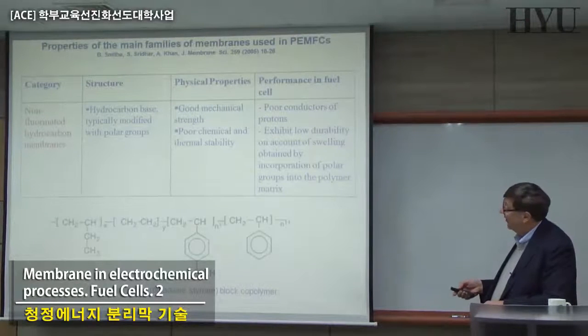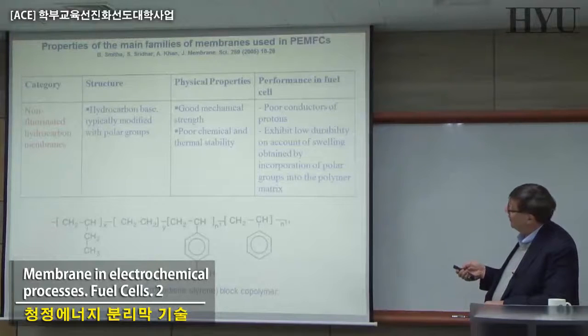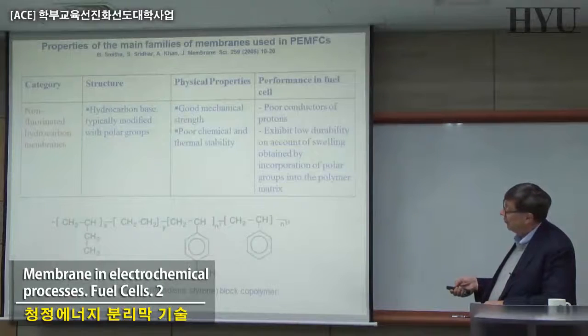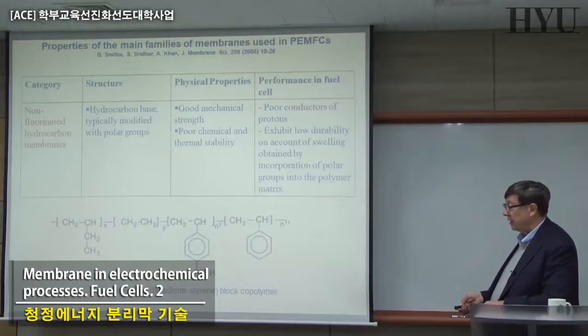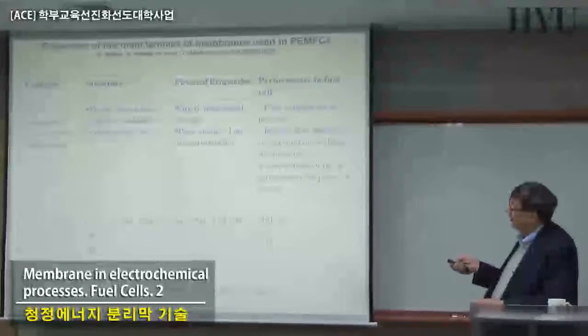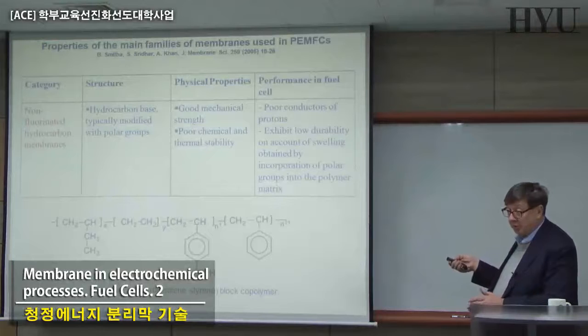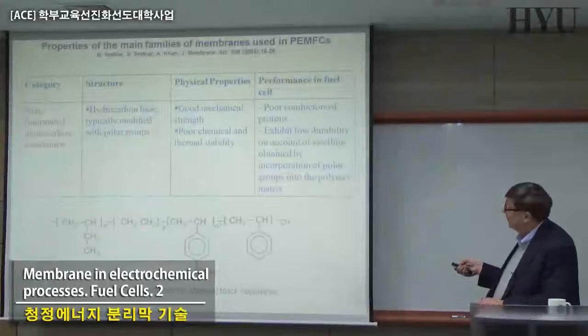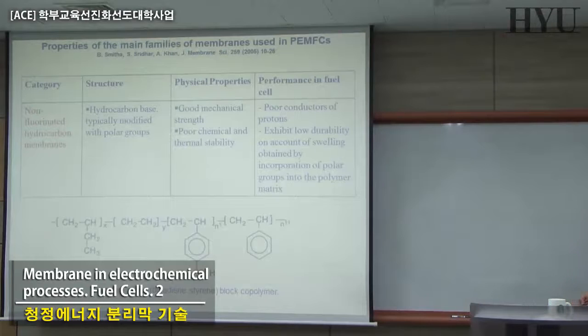Still not working. And now there is also, as I was mentioning, some cases in which the membranes are non-fluorinated hydrocarbons, and that is the case of this polybutadiene styrene block copolymer. But again, it has good mechanical but poor chemical and thermal stability, not very high proton conductivity, and the lifetime is not as interesting as that of other polymers.